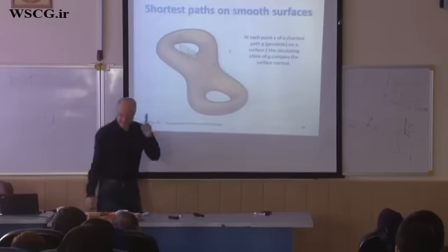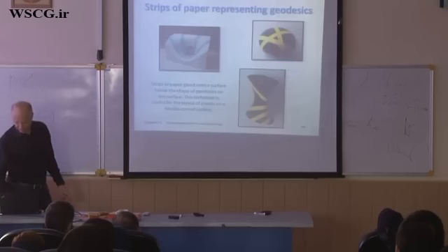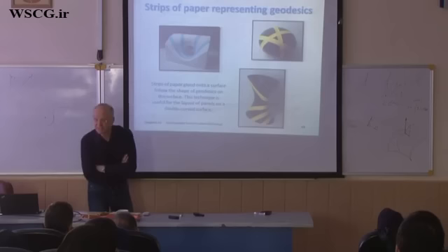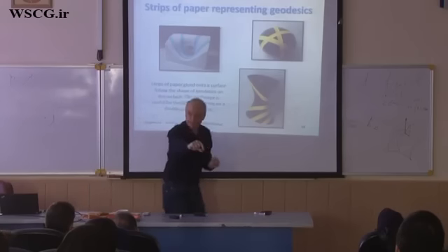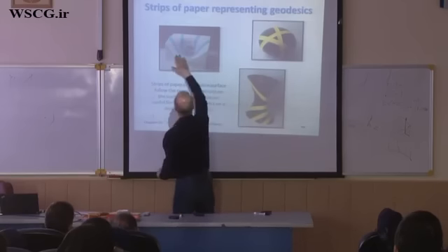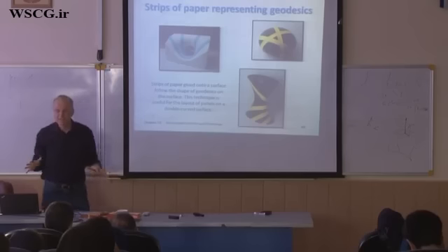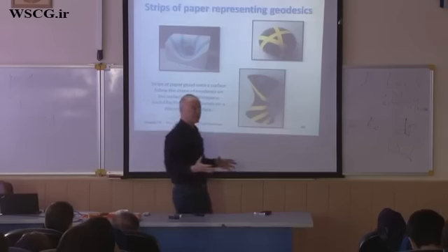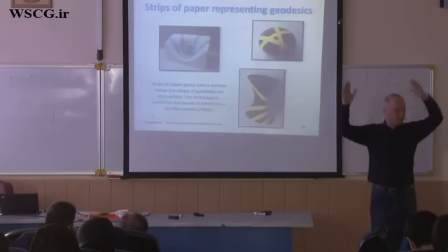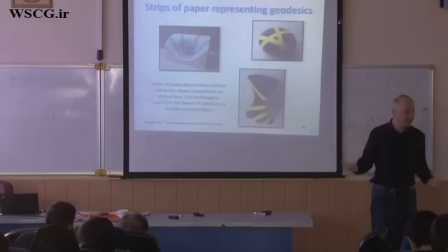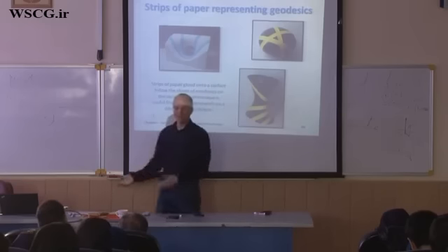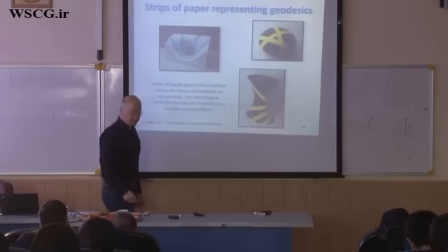Now, these geodesics are very interesting for applications because if we have a surface, now we have again our paper strip, we can take a straight strip of paper and glue it on the surface, and it will always follow a geodesic. So if you would like to panelize a surface with long, straight strips of bendable material, it will follow geodesics. Then I do not have the trouble of cutting so much off.